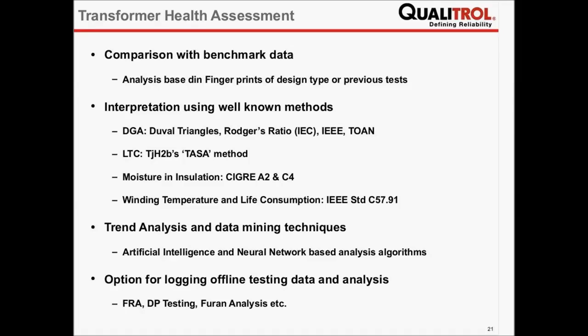A trend analysis and data mining techniques can also be implemented in this system. I was talking about having a knowledge-based database. That knowledge-based database should be used to develop artificial intelligence and neural network-based analysis algorithms, which will ultimately get trained on this fault database and the event database, and will be used to come up with the risk index of a particular transformer. And the transformer monitoring system should also have a facility to log the offline testing data.